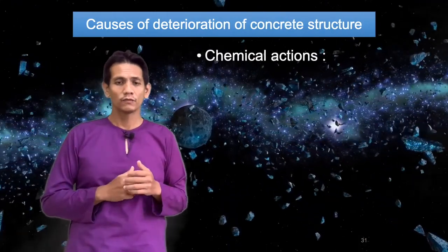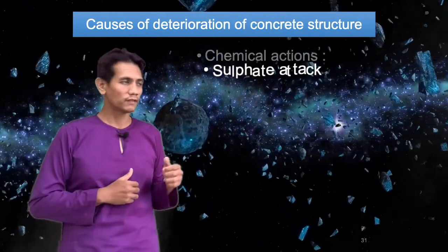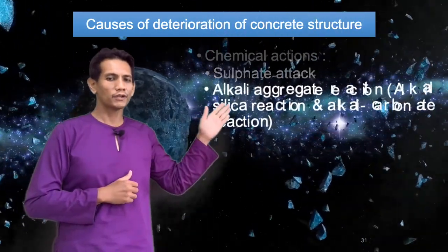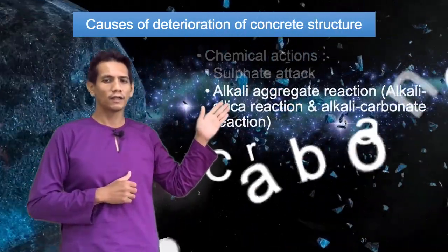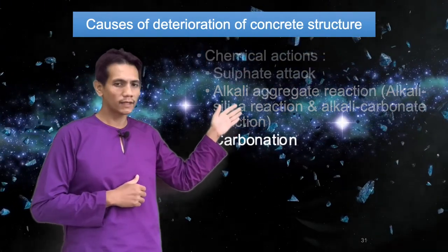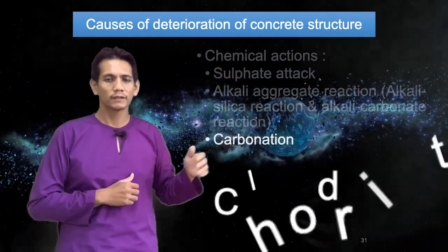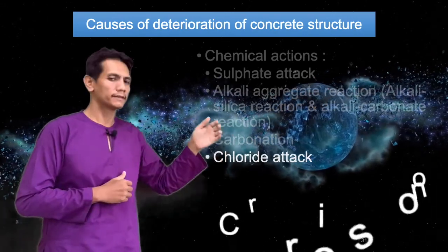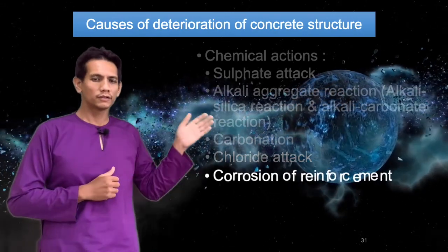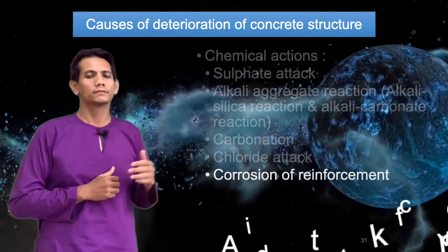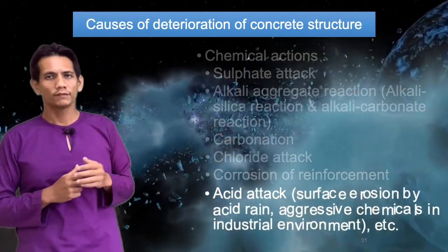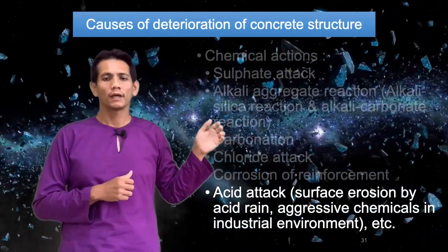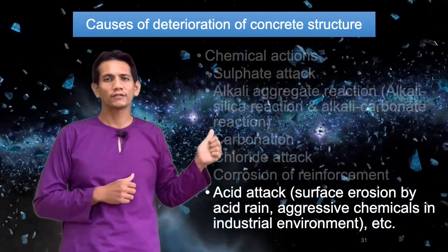For chemical actions, we have sulfate attack, alkali aggregate reaction, in terms of alkali silica reaction and alkali carbonate reaction, carbonation, chloride attack, corrosion of reinforcement. And then we have acid attack on surface reaction by acid rain, aggressive chemical, industrial environment, and etc.